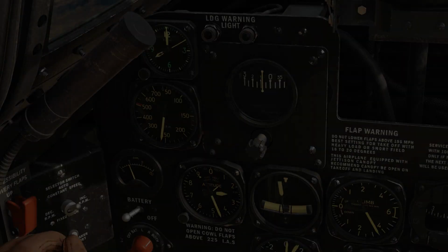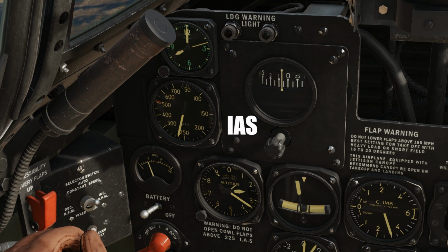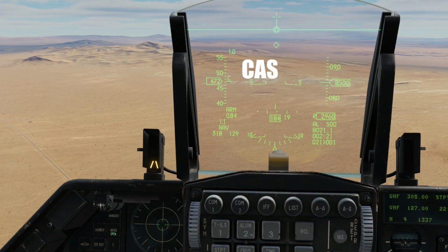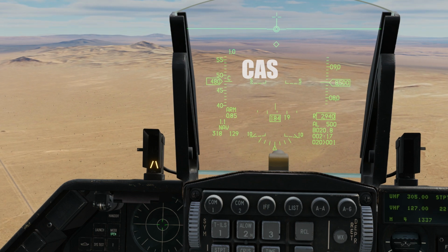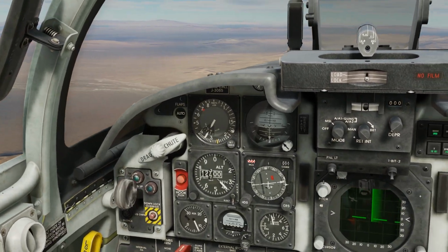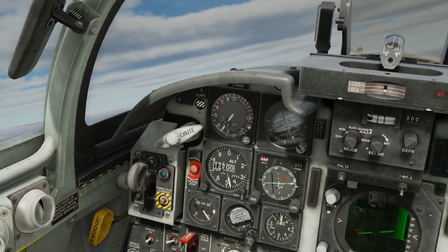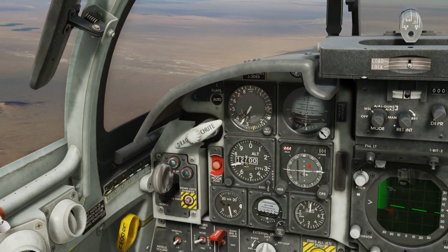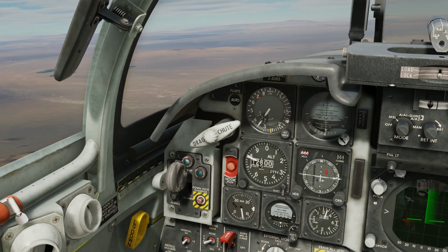The airspeed indicator in your plane can be either mechanical or digital. The first one will show you indicated airspeed, while the latter will display calibrated airspeed. To understand the difference between them, we have to think about the conditions of the measurement. The aircraft does not move on rails, it shifts about in 3 axes. As a result, the speed shown to you will be subjected to errors.